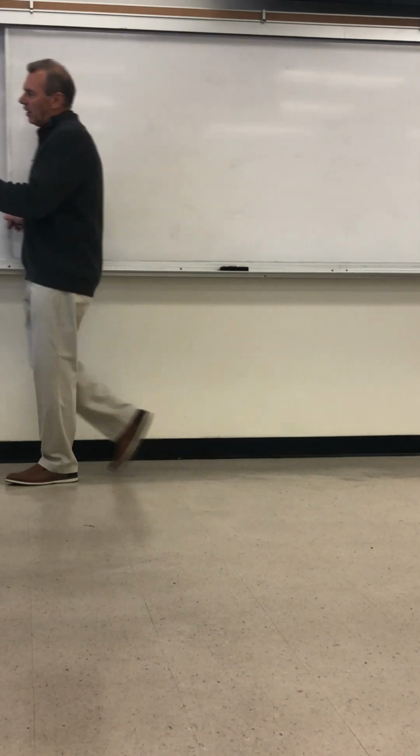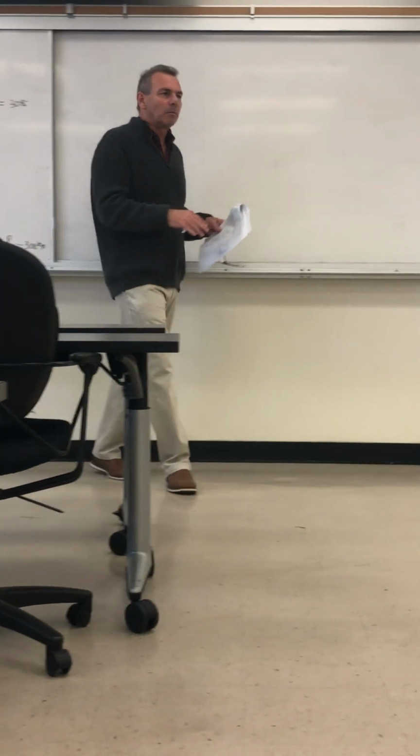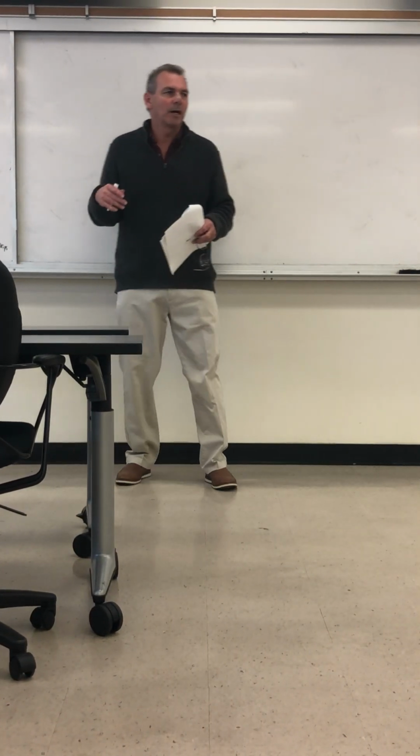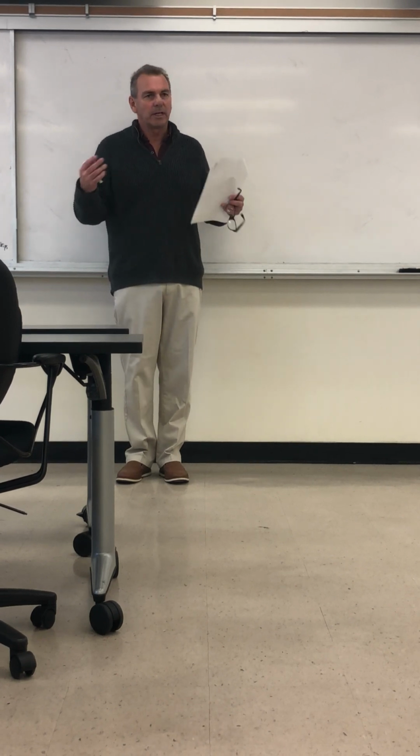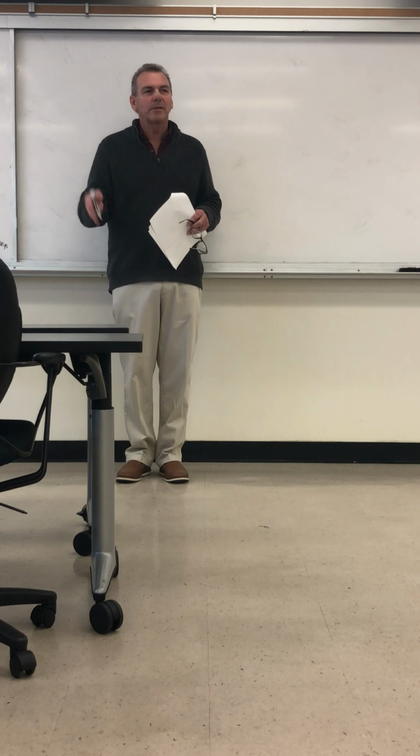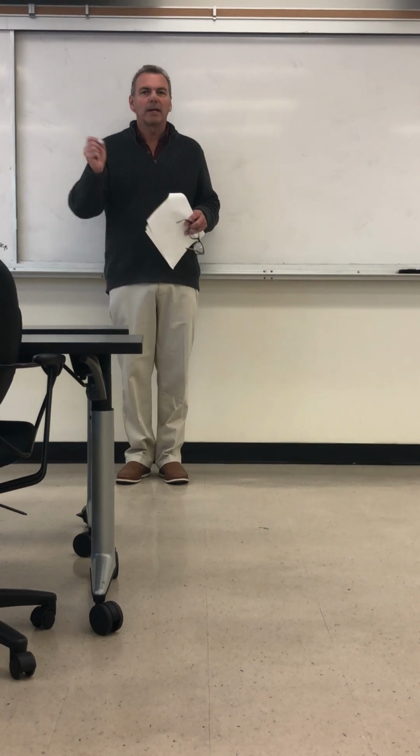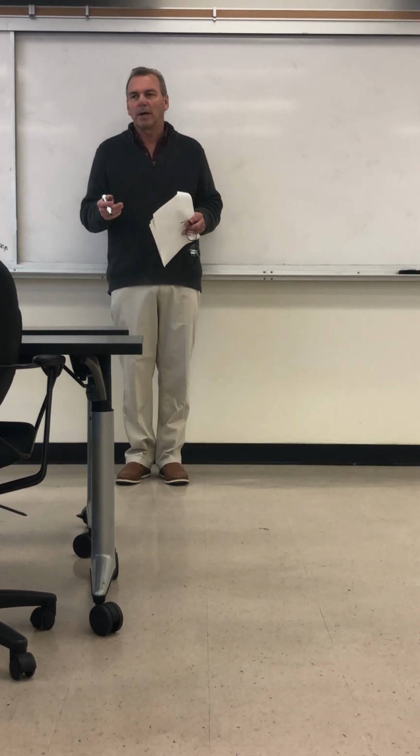This is important. We're applying loads, and right now we're just solving for the reactions. If you get your reactions wrong, then the rest of your structural analysis will all be wrong. And there's a long history of doing hand calculations, being able to solve things like what we're doing here. These are called hand calculations, as opposed to just blindly putting something in a computer program and having it spit out all the results. Even to this day, when I design a structure or do analysis of a structure, I always, 100% of the time, independently check by hand calculations and verify results by computer.